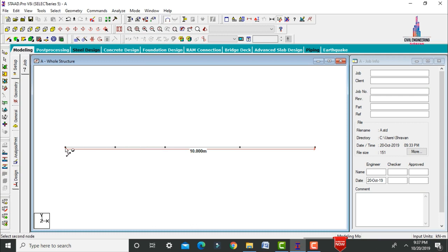After that, again we will check the internal section node points. Now we can select these options like this. By using these options, you can directly check whether it comes to a 2 meter beam or 3 meter beam. So it consists of 2 meter length, 2 meter length, 3 meter length, 3 meter length. Total length will be equal to 10 meter.